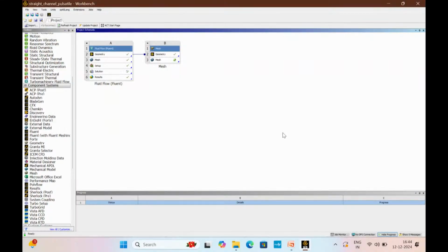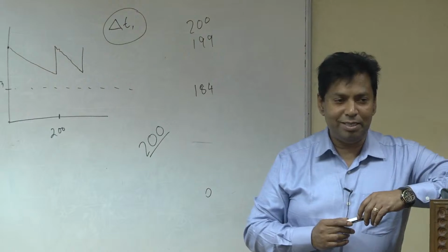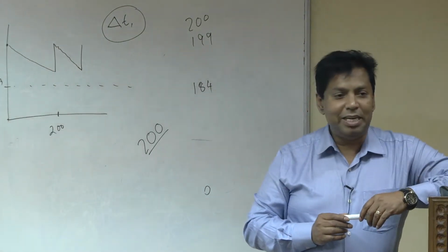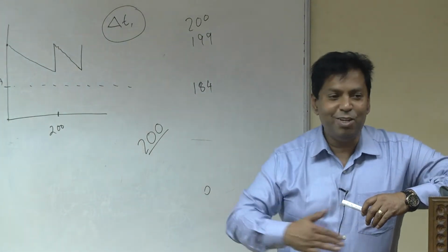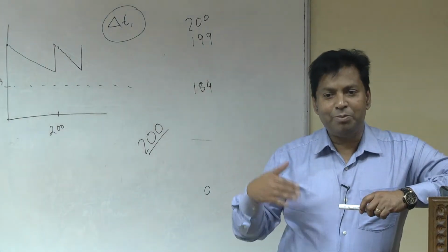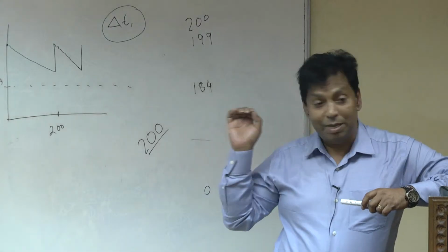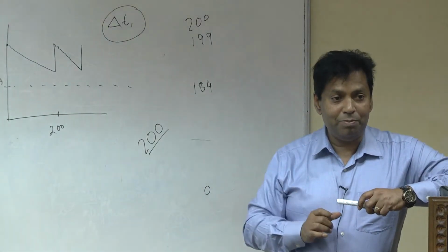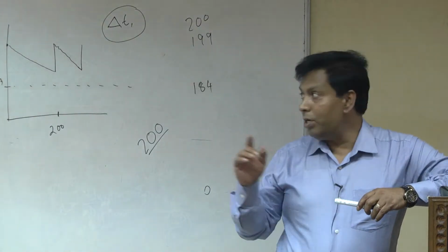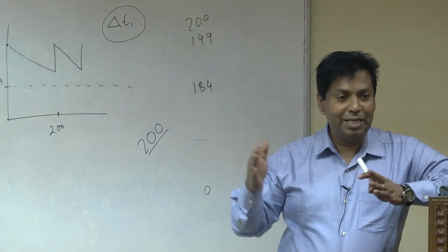Then you have to increase the maximum number of iterations. But there is another issue. Sometimes you cannot afford it. If every time step takes 500 iterations, it takes a long time to solve. So there are some issues. Okay? That time you have to do some debugging. Maybe your mesh has an issue, maybe your time step is very large. You have to make the time step smaller, or adjust the relaxation factor. So a lot of things you have to think about at that time.